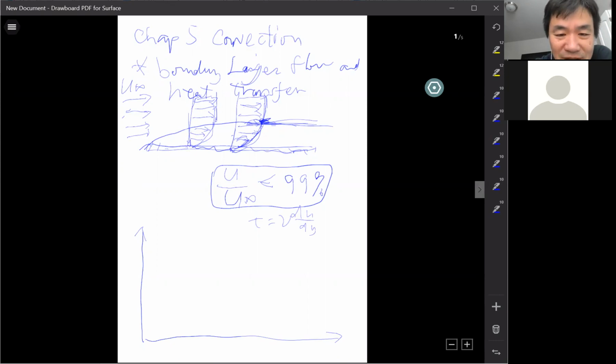So look at the shape of the boundary layer. Because the boundary layer thickness increases, the region depth increases. So the profile gradually becomes more gradual as x increases. Further along the plate, the velocity profile changes more gradually. If it's a gradual change, du/dy gets smaller, right? At the tip at the beginning, it's a sudden change. Immediately on the surface the velocity is 0, but immediately outside the surface it's just the free stream velocity. It's a big velocity that suddenly becomes 0. So your du/dy at the tip is very big, almost infinitely big.